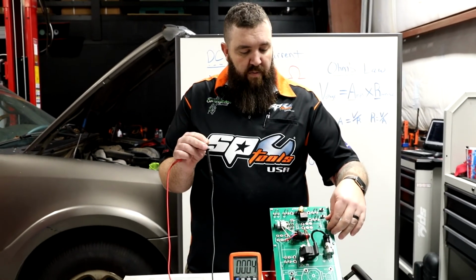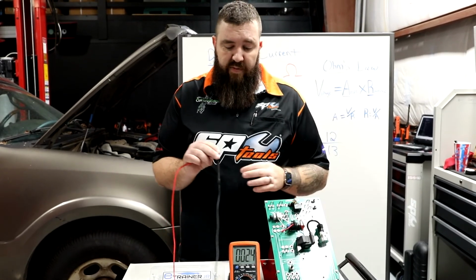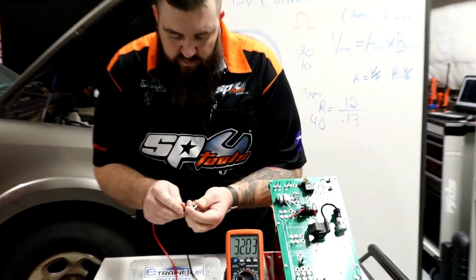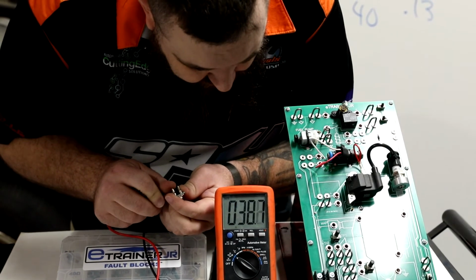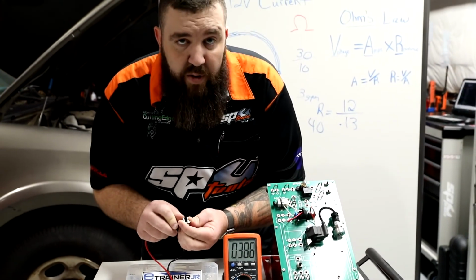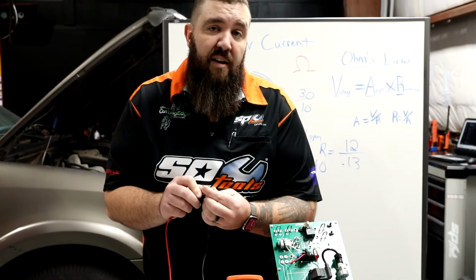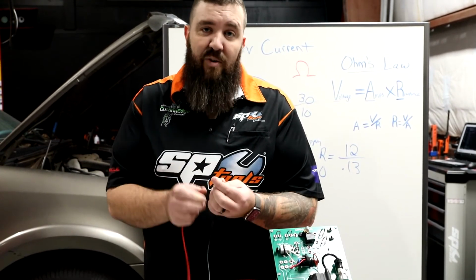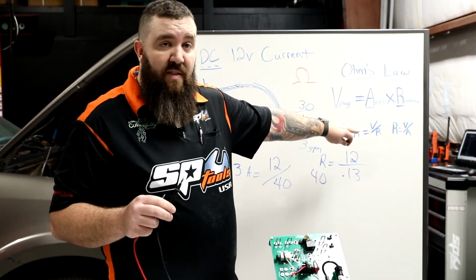Now, what we're going to do is we're going to take our fancy 40 ohm resistor, because we know the resistance value of this one. We're going to touch the two ends to our meter, and we can see our reading 38.7, which is really close to 40 ohms of resistance. So if for some reason you're trying to find the resistance value of a certain point in a circuit, then that's how you can use your meter to find out the resistance value within this circuit.